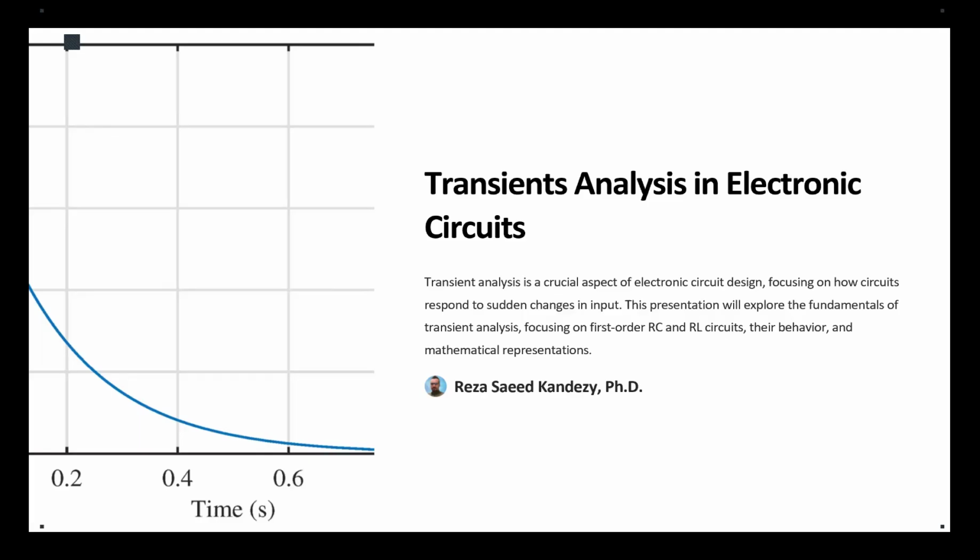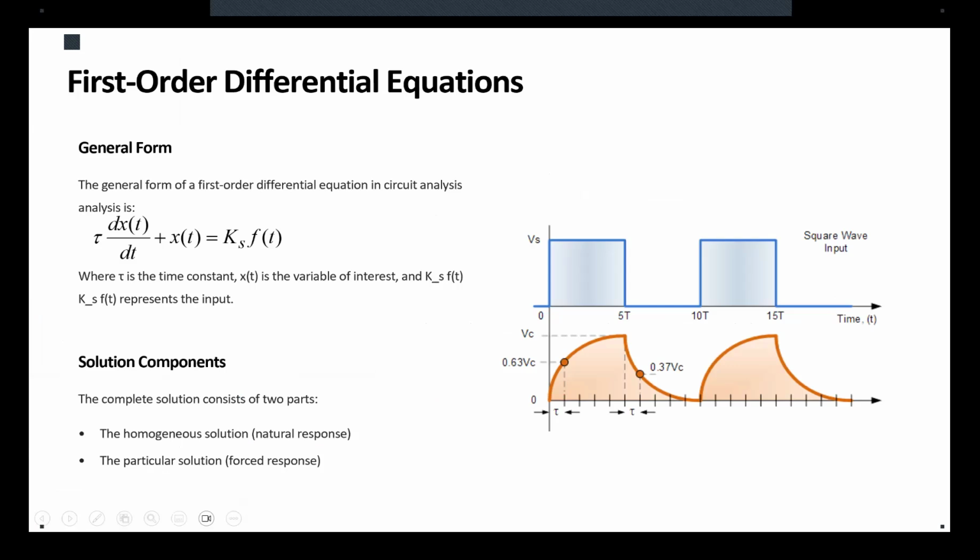Now, when we talked about the DC system, we always consider the capacitor and inductor. When we talked about the steady state in the DC system, we consider those two components as components that would not affect our analysis. So we basically replace the inductor with a short circuit and a capacitor with an open circuit. Then we have a steady state DC. Now, when we have a transient, we cannot